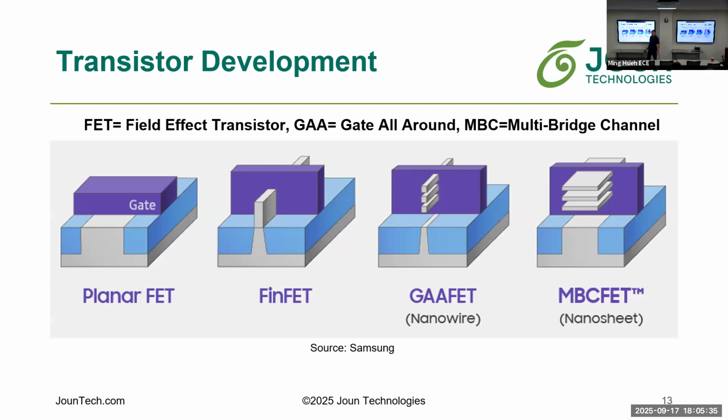Why is there innovation here? Well, the problem is as you start to shrink smaller and smaller and smaller, eventually you get to a spot where you can't shut this off because these two parts of the switch are so close together. No matter what signal you put on the toggle in the middle, it just will not shut off. And how annoying would it be to be in a house where you shut all the switches in the house, but the lights don't quite go off, right? So that's why they've had to come up with new designs here that will, in fact, ensure that this transistor continues to operate like a switch as we go to smaller and smaller dimensions.